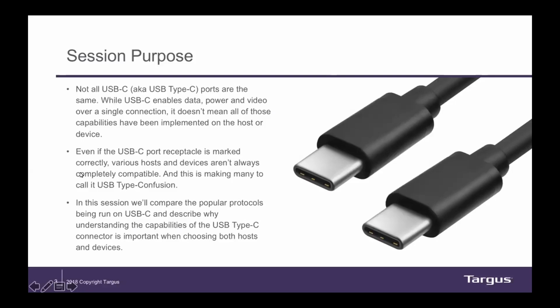Next, even if the USB-C port receptacle is marked correctly, various hosts and devices aren't always completely compatible. And this is making many call it USB Type-C for confusion. And in this session, we're going to compare the popular protocols being run on USB-C and describe why understanding the capabilities of the USB Type-C connector is important when choosing both hosts and devices.